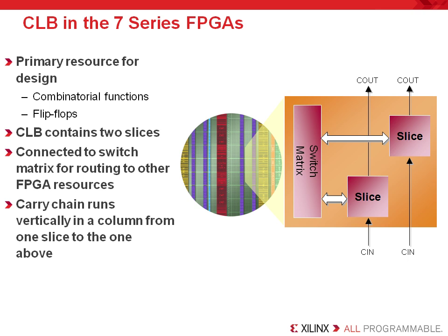Now the Virtex 6 and 7 series of Xilinx FPGAs contain essentially the same CLB logic resources. So if you're used to working with Virtex 6, the adaptation to the 7 series is actually pretty easy. Now slices are grouped into configurable logic blocks or CLBs and contain combinatorial logic as well as register resources. As you can see from this picture, there are a lot of CLBs on the die.